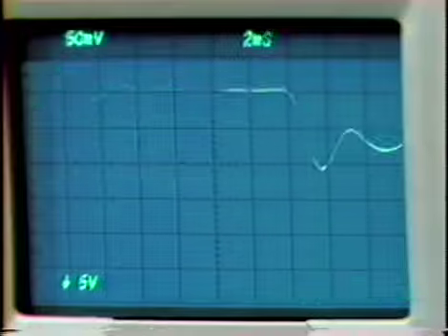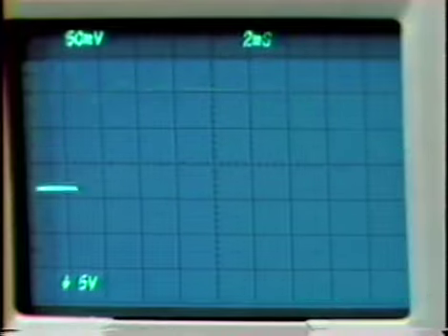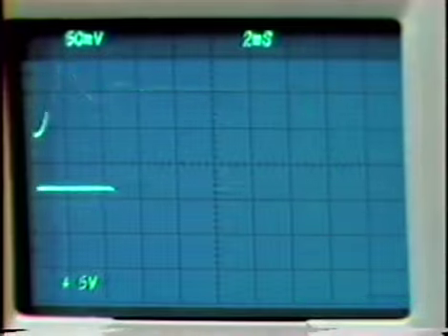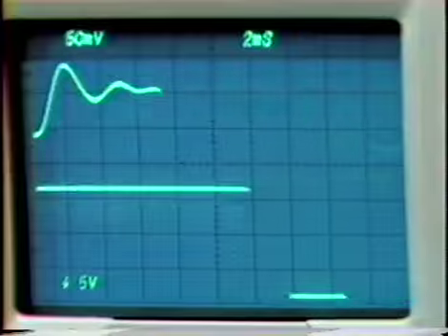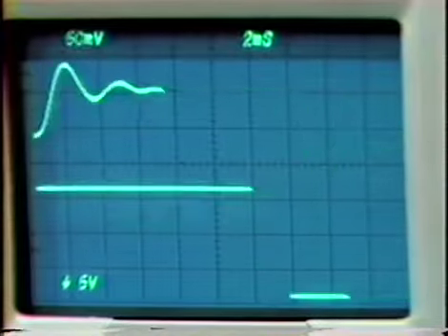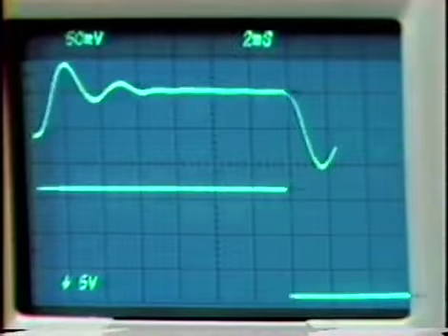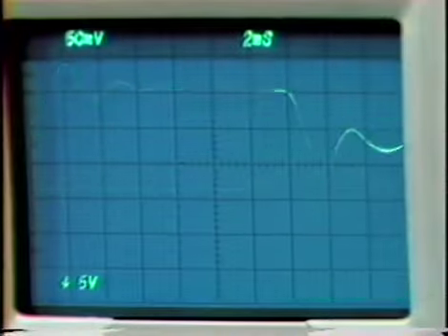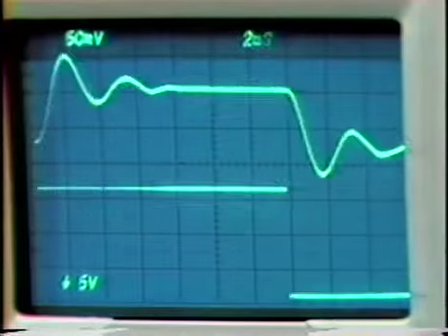So there's something just a little bit funny about the response of the system, and that reflects the nonlinearities associated with the phase detection process and the difficulties of maintaining lock for large ranges of signal. We can make that problem worse by increasing the amount by which we change the command input.